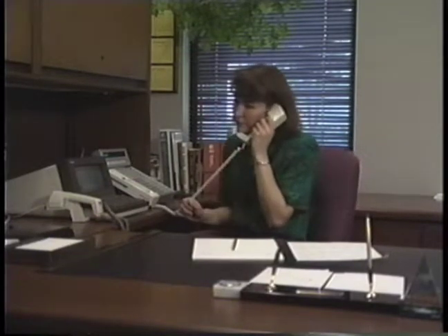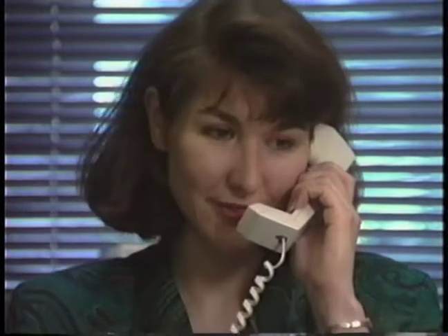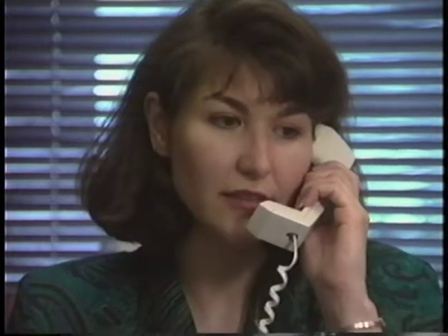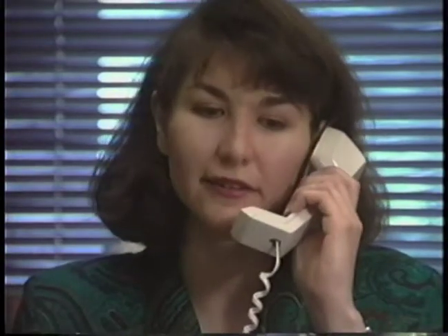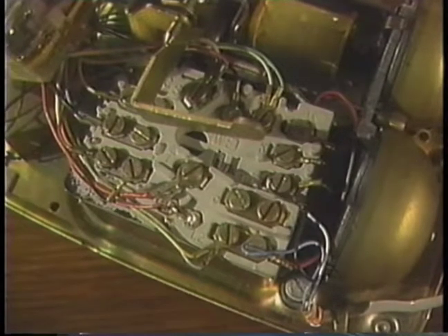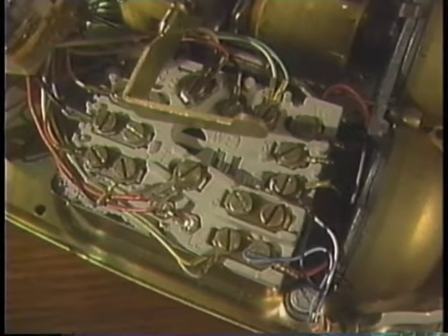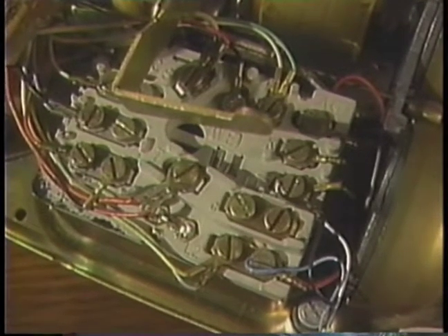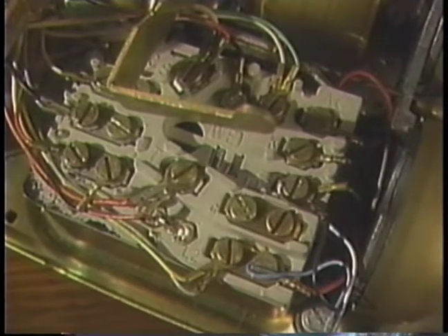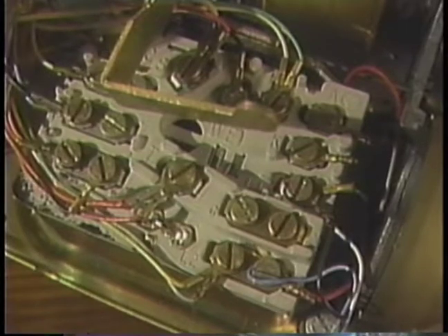The hybrid coil incorporates a device called the balancing network. This allows someone speaking into the transmitter to hear their own voice in the receiver at a volume close to the other person's voice, so the person speaking can make sure they don't speak too loudly or softly. The hybrid coil and the balancing network work together. Both devices allow full duplex transmission along the 2 wires between the telephone and the central office. Full duplex means that signals are transmitted in both directions at the same time. This conserves the number of wires required to serve telephone customers.